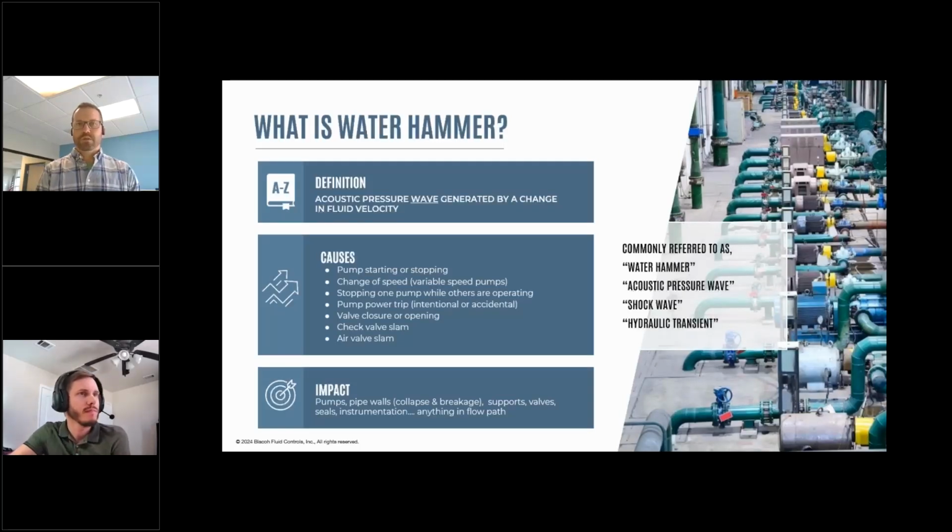As you've heard before in the previous webinars, what exactly is WaterHammer? Well, it's an acoustic pressure wave generated by a change in fluid velocity. And that's a nice way of saying that we have a change in the system. It's a transient event. A system is operating at a steady state condition, and then we change that condition to some other condition.